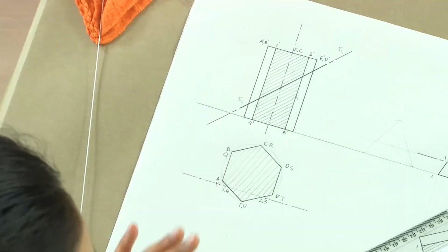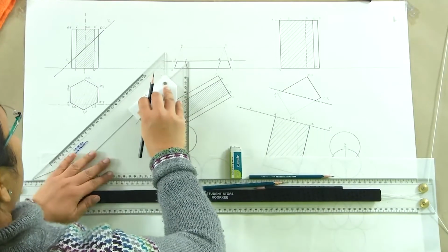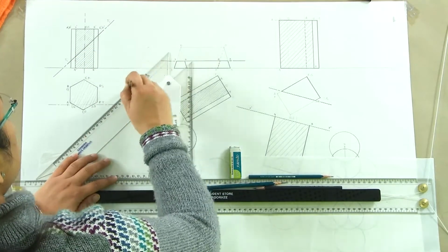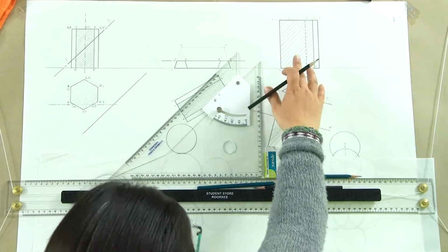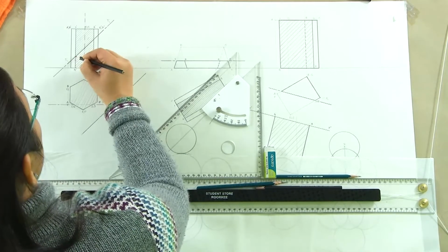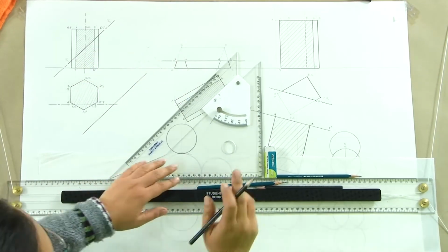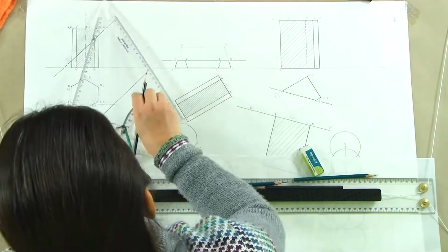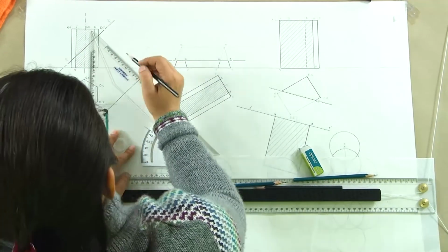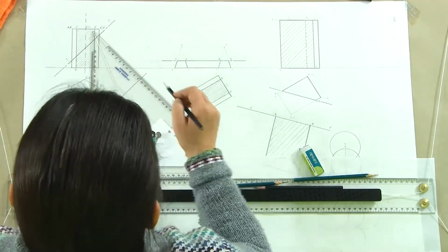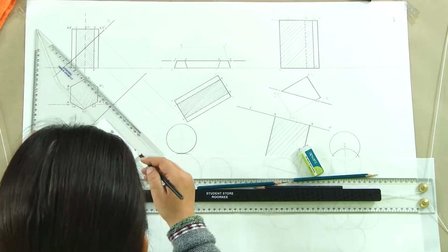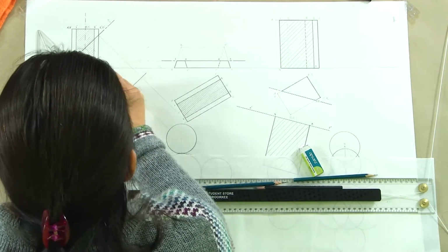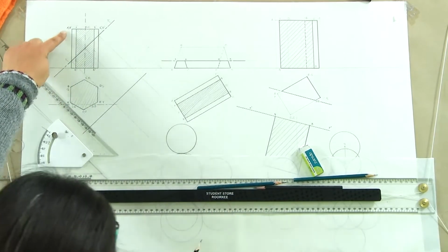Now how do we see the true shape of the section, which is required? Again we have to draw an auxiliary plane parallel to the section plane. So I am drawing this xy here. Now, similar to what we had here, we have the same things. This distance is going to remain intact. So we will just draw, this is where D and E are going to come. This is the point where F and C are going to come, and this is the point where A and B are going to come. That is how we are getting.